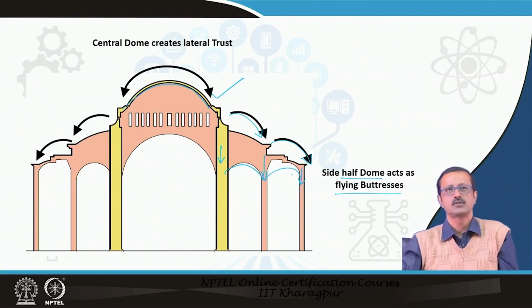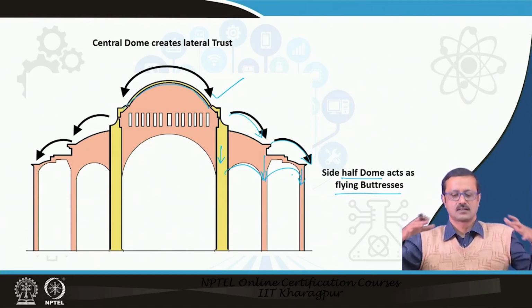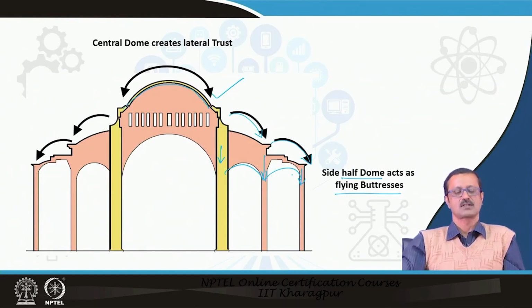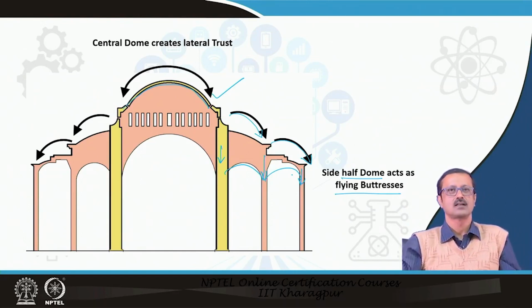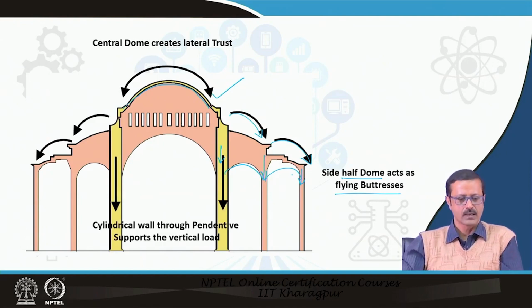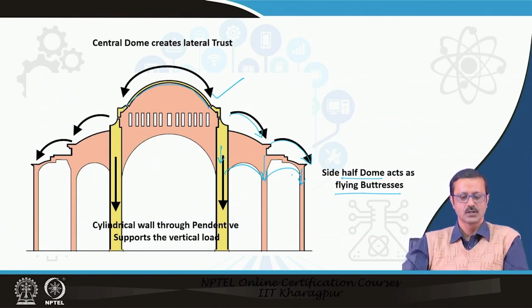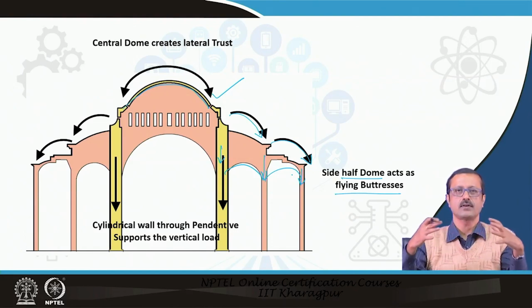So, if you go to Istanbul and visit this particular World Heritage Site, you will definitely see the half domes there. And they are taking care of the supports also, and the basic principle of the supporting system of the flat Byzantine dome is something like that. They created the half domes at the sides to take care of the load, and also the cylindrical wall surrounding that flat dome, with pendentives, takes care of the vertical load downward. So, a series of arrangements.